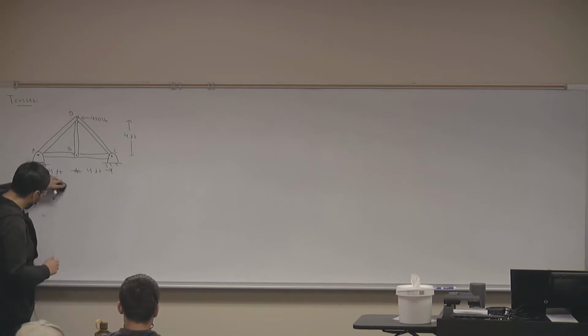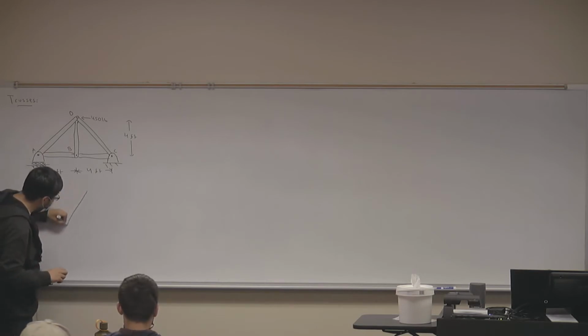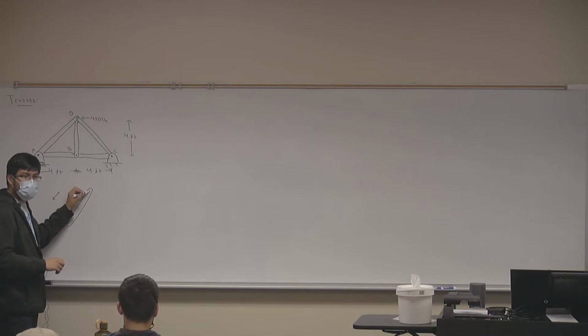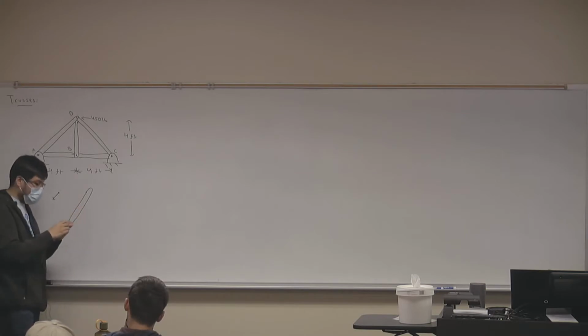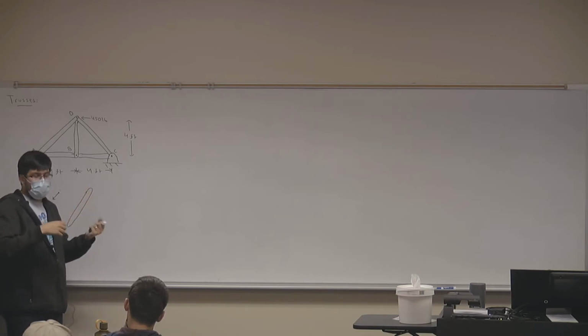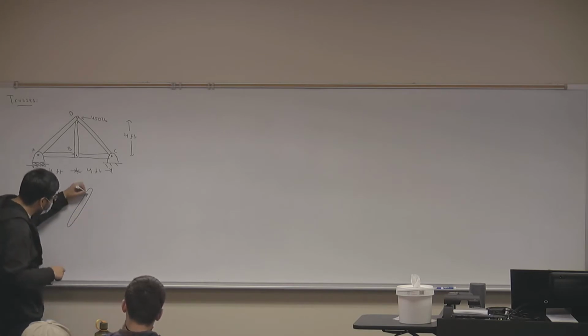Okay? However, if we're studying the truss, so instead of looking at a particle, if we're studying the rigid element that is the truss, and the truss is experiencing tension, in which direction would you draw the force? Inwards. Outwards if you're studying the truss, right? So, like I said, we're looking at two different things. The joint individually will be outwards, but if you look at the truss individually, let's say I hold the two ends of the truss and I want the truss to experience tension. What am I going to do? Am I going to push in or pull out? Pull out. Okay, so the truss is going to be experiencing a force in the opposite direction.